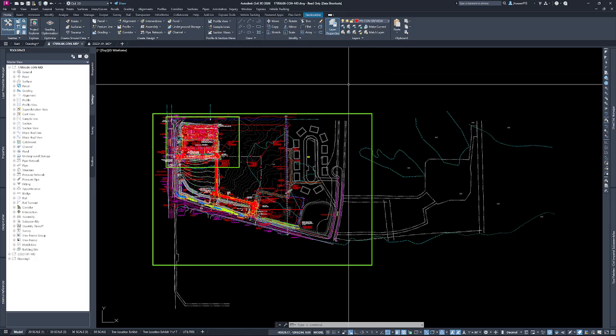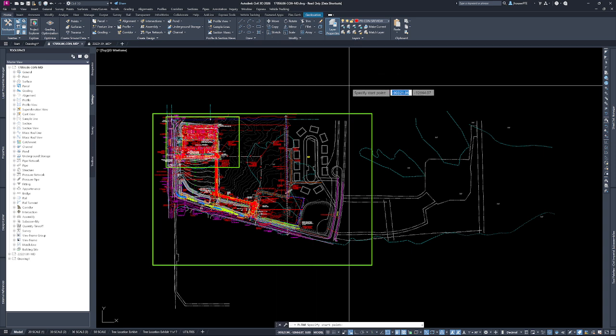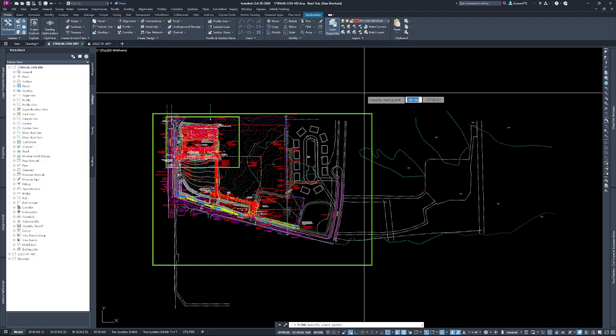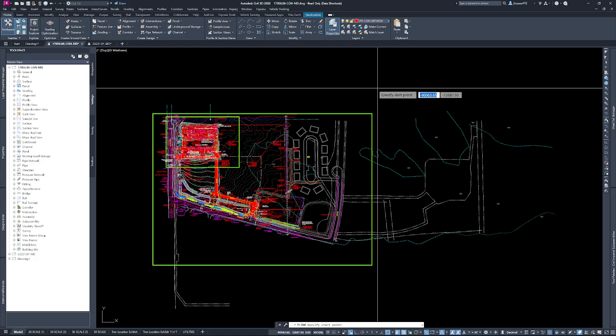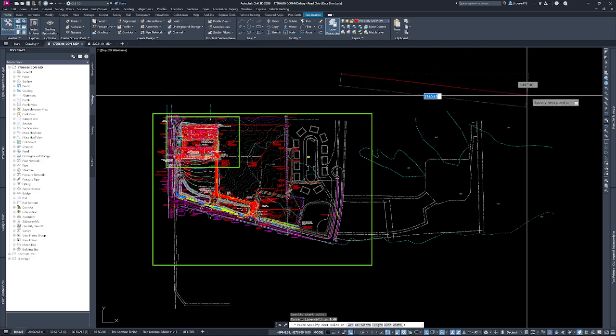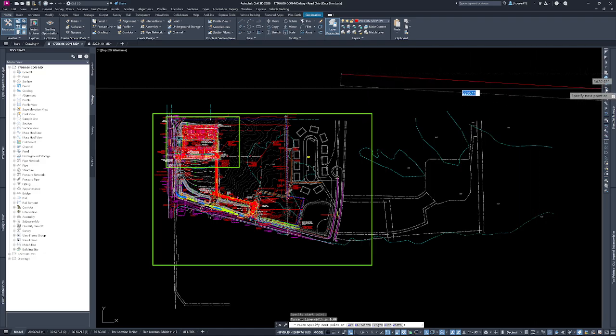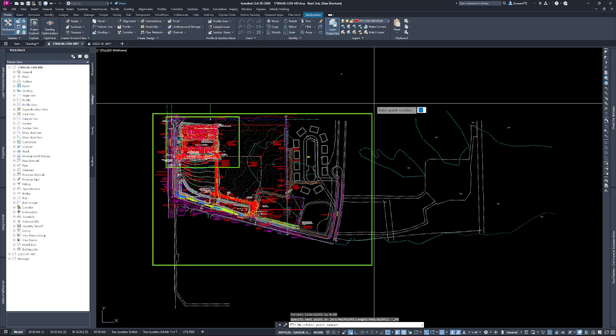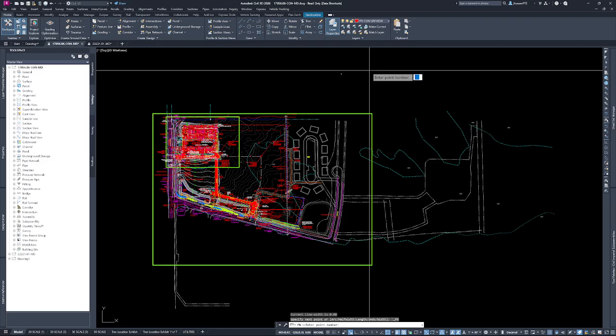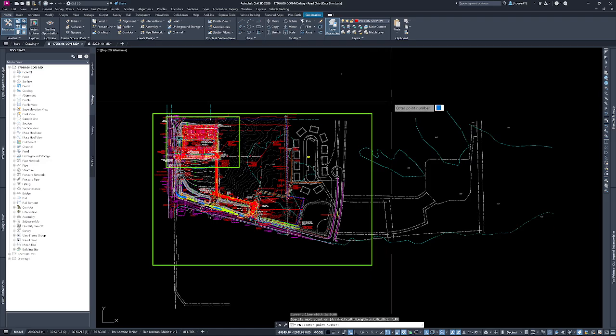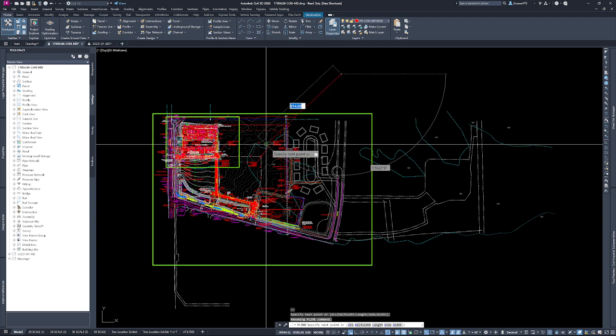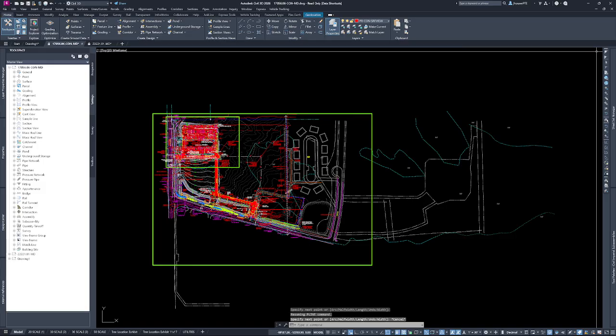The one I used to use quite a bit was I would draw a polyline, or when we were creating base maps and doing the line work and it wasn't automated and I needed to connect the dots, this was the command I went to. I would do a polyline, I'd snap to a node, and there's an option here to say, I'm going to use this one right here, and then I can set enter points. You look at your point numbers, and you say, I need to connect point 100 to 150. You type 100-150, and boom, it would connect all those points right away with the polyline. And when you're done, you would hit escape, and you're back into the polyline command. So these can be very useful.